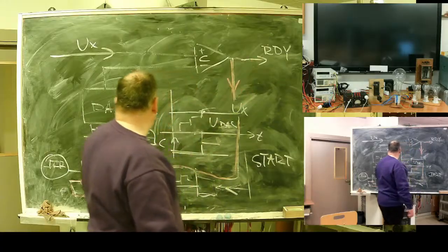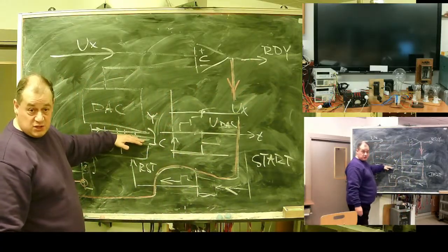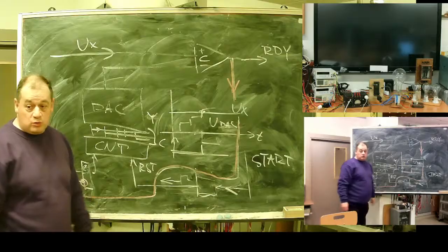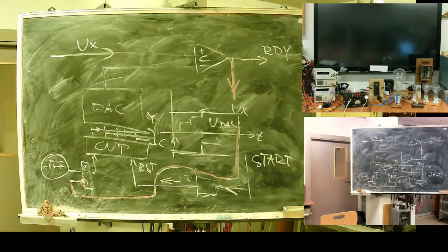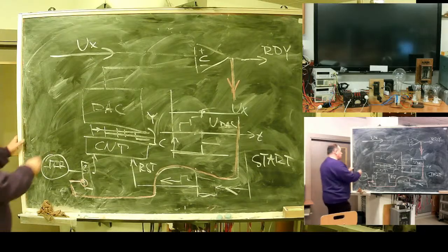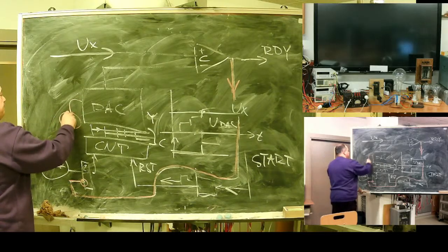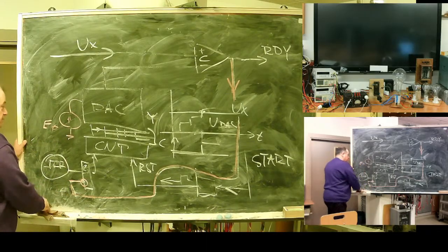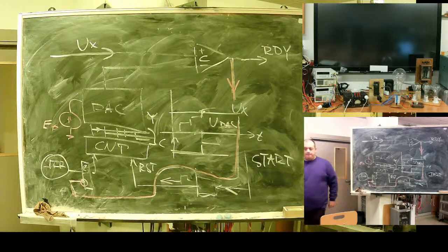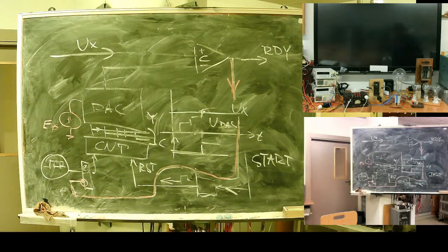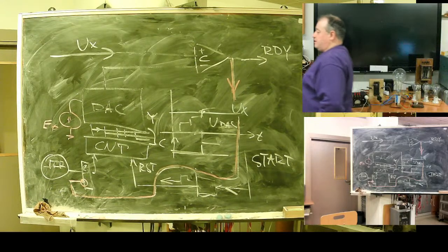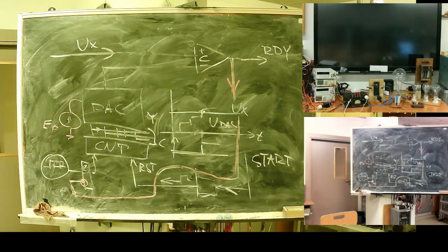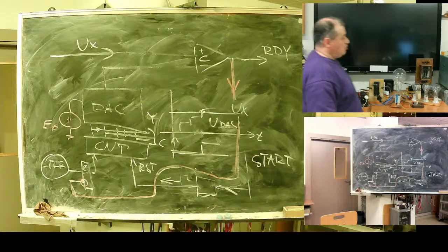On the ready signal, the processor reads the contents of the counter, and it's our voltage measured in units of what? In units of the DAC reference. We will get our voltage measured relative to the reference voltage of the DAC.